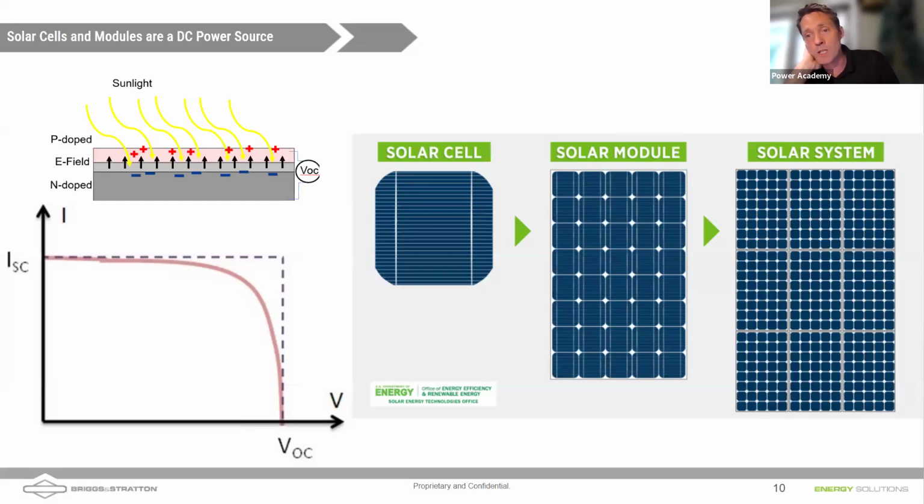Additionally, we're also seeing a lot more split panels, Daniel, split cell, where we've got essentially the top half of the panel and independently producing electricity from the bottom, and those two paralleled. So that can help in shading issues as well.